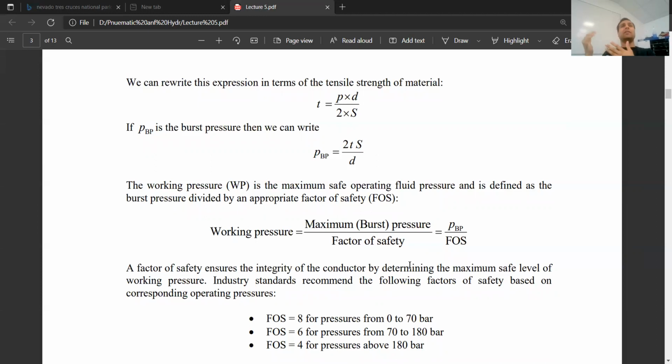Because obviously it's a lift. But if the component is quite expensive, pricey, and quite crucial to the whole system, for example a space shuttle, they will need to use a factor of safety of more than 2. They might use 10, they might use 15, they might use a factor of safety of 8, because if the component fails, there might not be a person to fix that thing straight away.